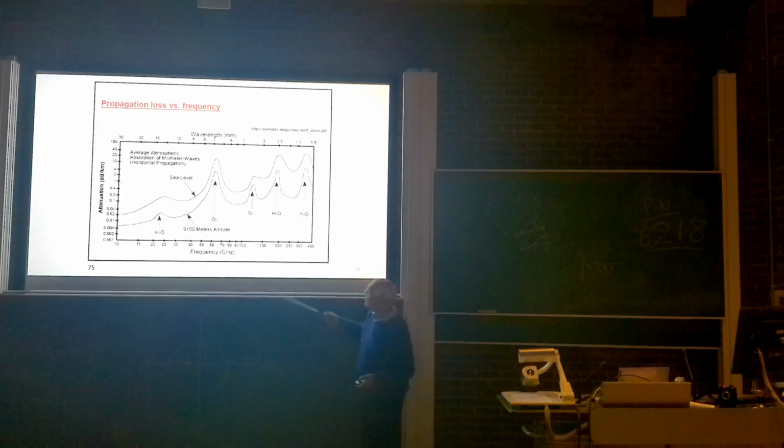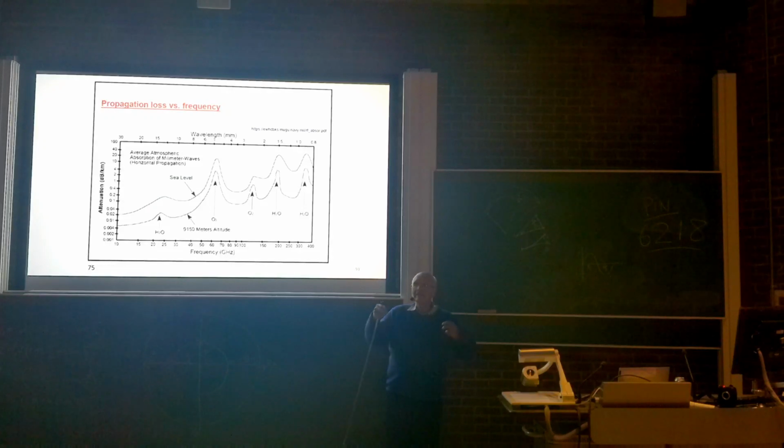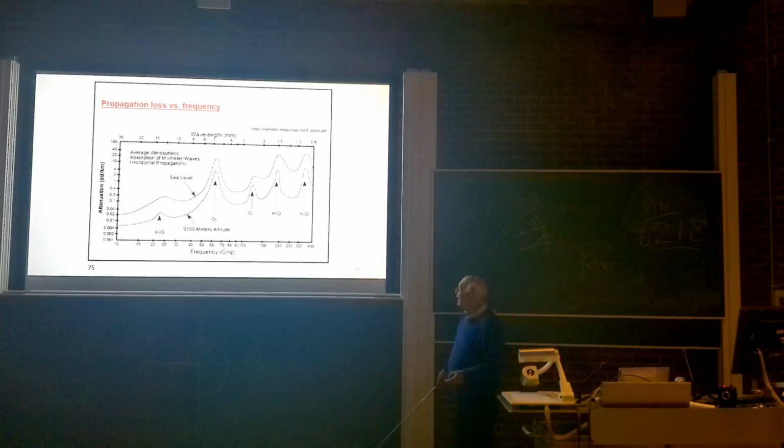Now this is the band which is used for car radars, because it actually means that you can get a short distance very well, but it cuts off very rapidly. The attenuation drops off a bit like a stone. There are other ones, so we're moving up into the sub-terahertz band, so there are still problems. So you have to choose the right places for where you operate it.